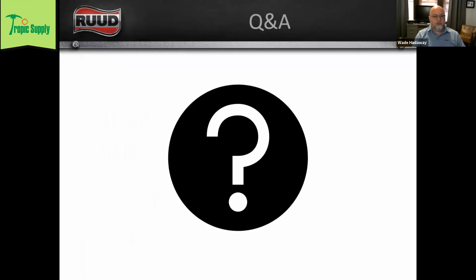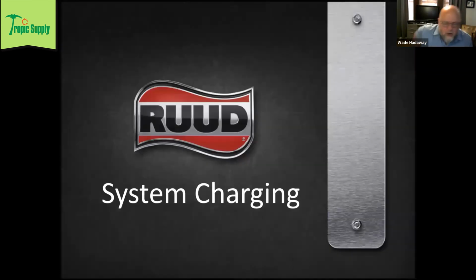We're going to talk a little bit about charging. I'm going to skip over this Q&A. We're going to talk a little bit about system charging. I want to preface this by saying don't ever put your gauges on a unit or start charging a unit before you verify airflow. The charging charts that I'm about to show you are all built on the assumption that the indoor airflow is correct. And depending on what that system is, or depending on that matchup, it might not be 400 CFM per ton, which is what we were all taught, right?